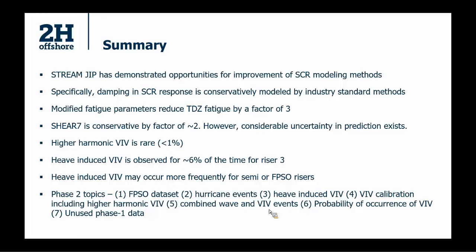I think we did just get a couple more. I'm just going to squeeze one more in. It is mentioned that higher CD values were used for the best fit data. How much would the CDs increase, and how do these numbers compare to the experiment and models? Again, I cannot give you the exact CD value because of confidentiality reasons, but I can tell you that they compare very well to test data. MIT did a bunch of tests, and they saw that strake CD can be really high in low KC flow. I would say our assumptions were in line with MIT's experiments.